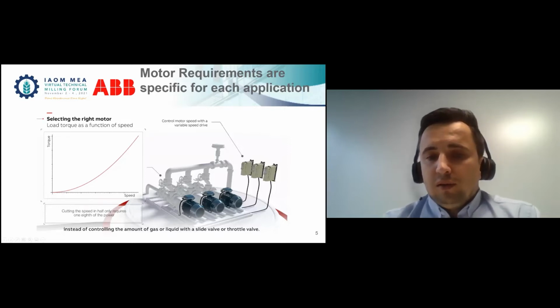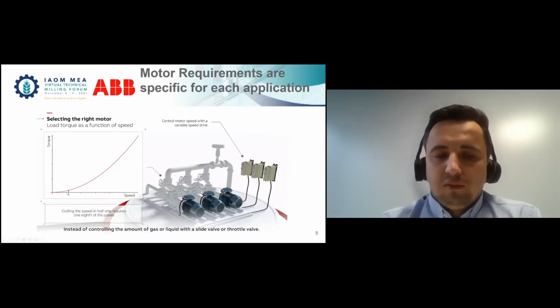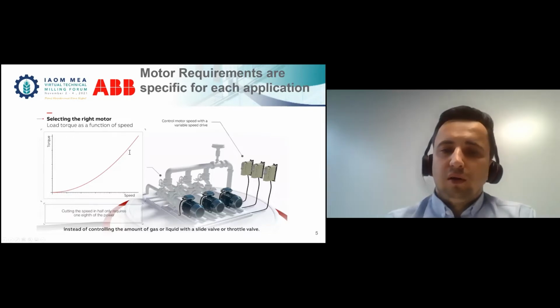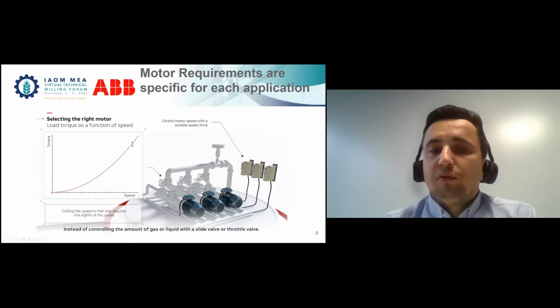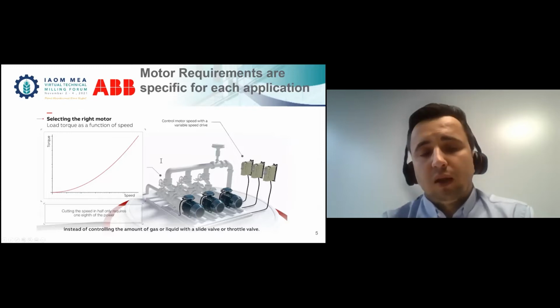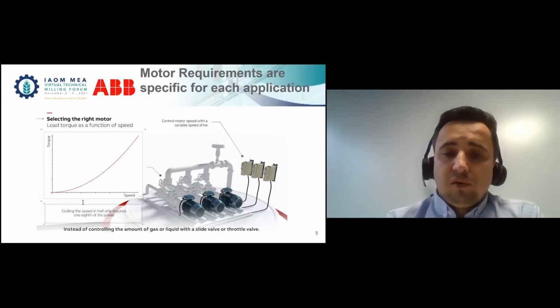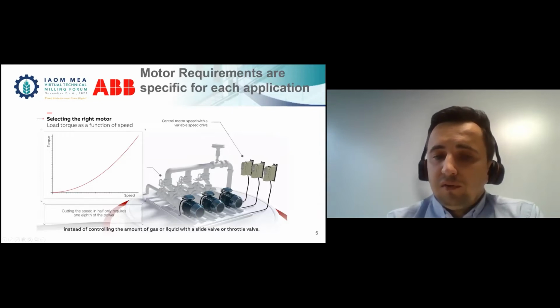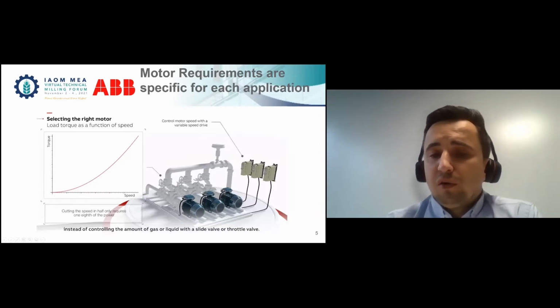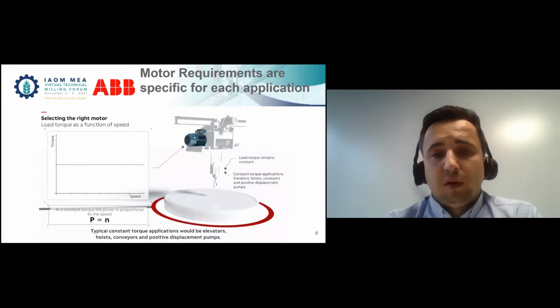With low speeds we usually generate very low power and low torque. This application is very suitable for energy savings or variable speed control, to save a lot of energy. We can go to the topic of energy savings later. We also see that the mechanical interface of the motor is on an aligned shaft, so there is no stress for the bearings, no belt, and we can use standard bearings, as an example.